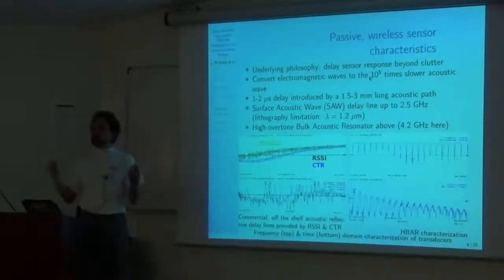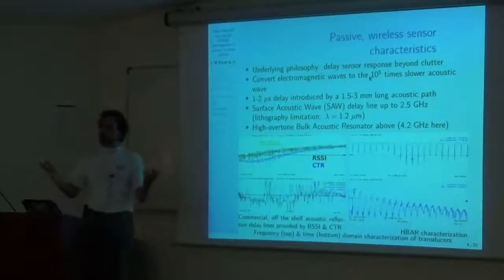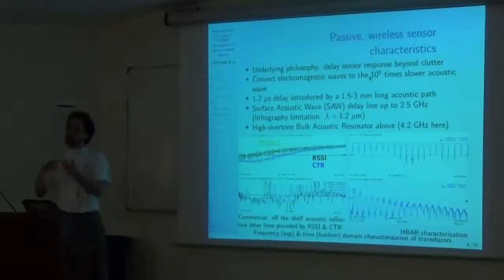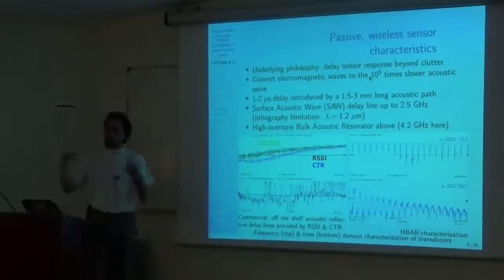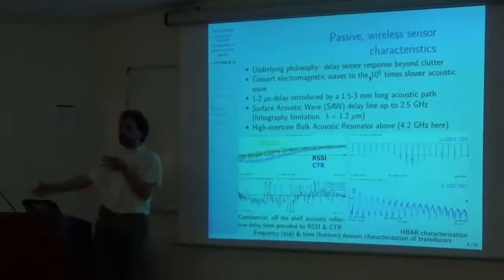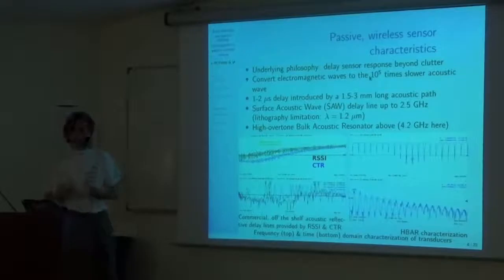This means that if you want to make a filter or resonator in which your wave has to travel multiple times your time delay, a coaxial cable introducing a time delay of 1 microsecond will be 150 meters long. An acoustic wave device will shrink this dimension by 10 to the 5, so it will be 1.5 millimeter long. So the rationale of making filters and resonators, you might all be familiar with crystal resonators when you clock a microcontroller. All these techniques using piezoelectric substrate to shrink the dimensions are the reason why you can make high efficiency filters in your mobile phone, and you don't have a mobile phone that is about 2 meters long, because you can shrink these dimensions by 10 to the 5 by converting electromagnetic signals into acoustic signals.